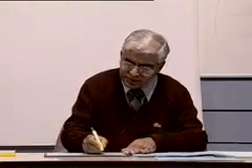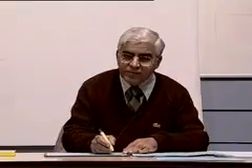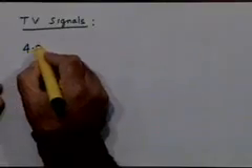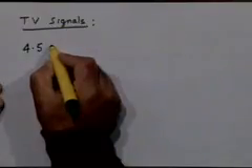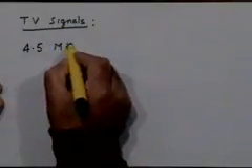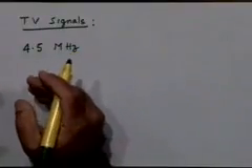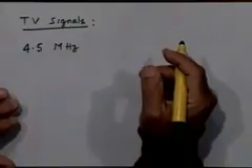Typically, it turns out, and I am just giving you information, which is a good point for comparison with the other signals, for the TV signal the bandwidth requirement is to the tune of 4.5, not kilohertz, but megahertz. So as you can see, it's 3 orders of magnitude higher than the bandwidth of a speech signal. So the bandwidth requirements of a picture signal will be much higher than those of a voice signal. And therefore, a communication system that you have designed for transmitting voice signals will be of absolutely no use to us when it comes to transmitting TV signals.